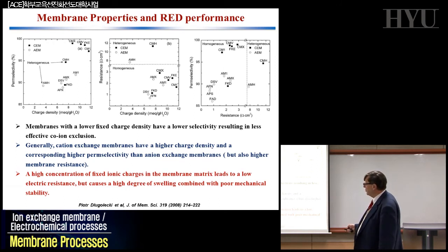And normally cation exchange membranes have a high charge density, and they are the best ones, as I was mentioning before, compared to anion exchange membranes. Anion exchange membranes normally are less effective. We don't have very good ones for this kind of phenomena, plus fouling, and the possibility of interactions that neutralize some of the charge and decrease the perm selectivity, basically.